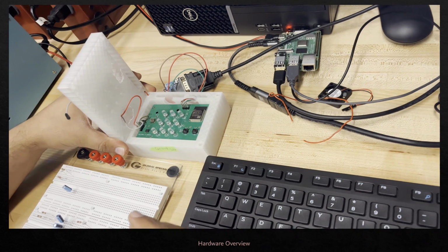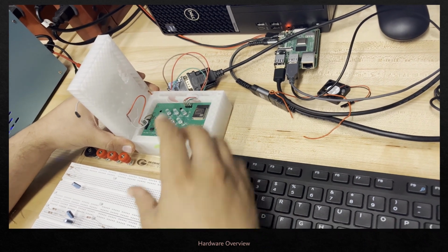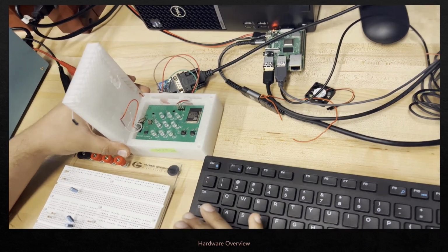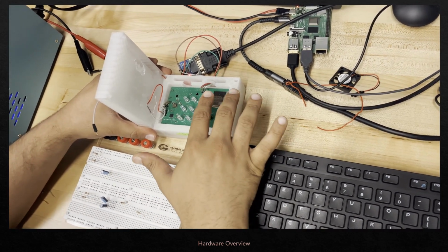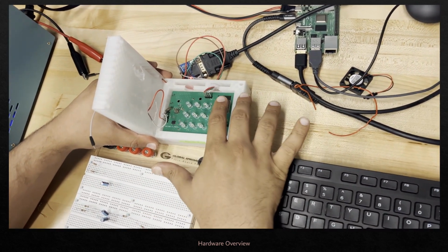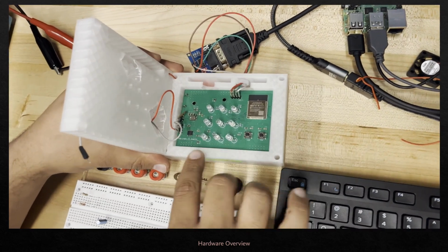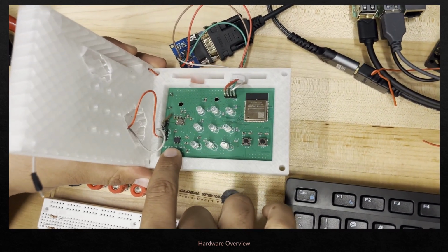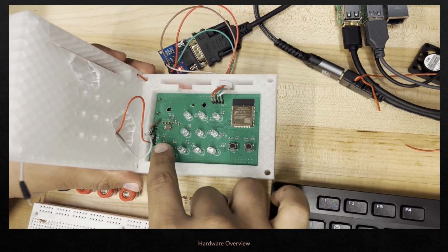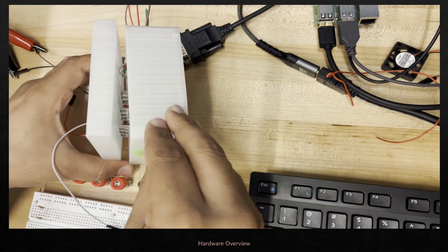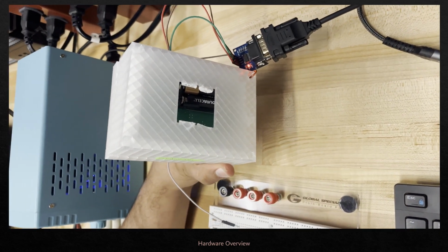So this is our advanced breadboard hardware specifications. We're going to be showing you all the hardware components and how they connect with each other. Over here, this is our PCB for the advanced breadboard. We have connected the LEDs, the ESP32, two buttons, the INA219, which is the current and voltage sensor, and then the voltage regulator, the TPS61023. In the back of the PCB, we have the switch and batteries connected for easy access.